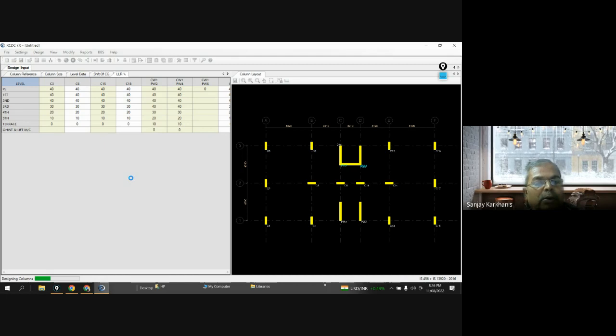But if you are going with design by ETABS itself, the requirement of ETABS is that if you want a reduction of the live load at the time of design as per your codal provision, then in the primary load cases, when you are defining the primary load case, you have to define it as reduce live load.